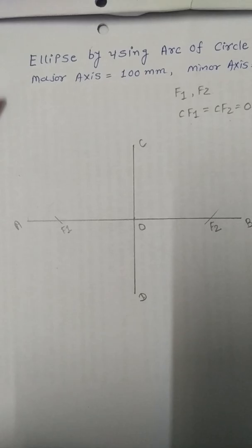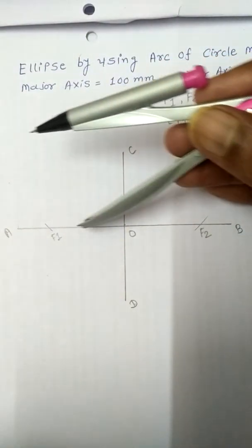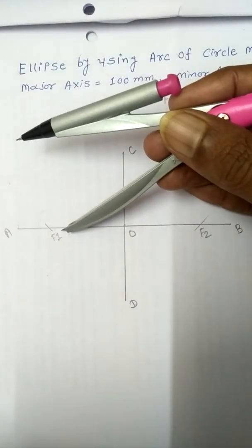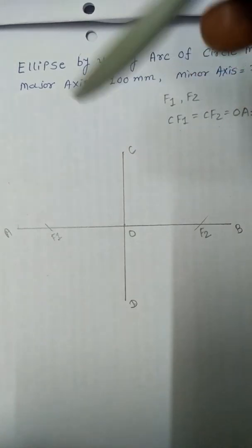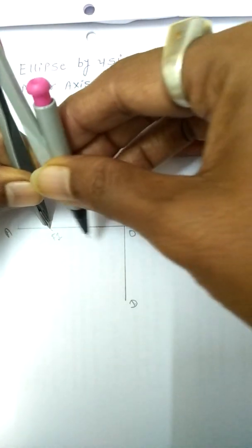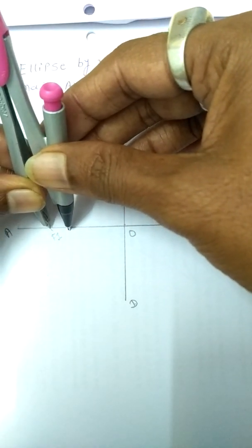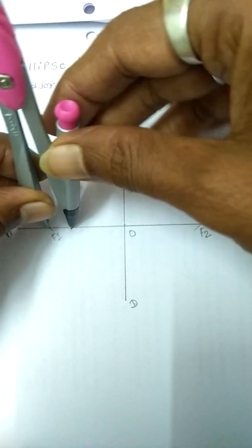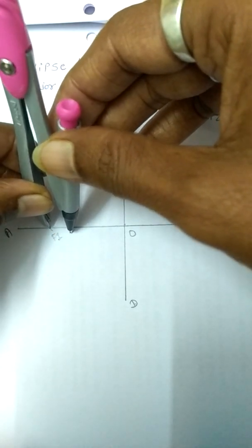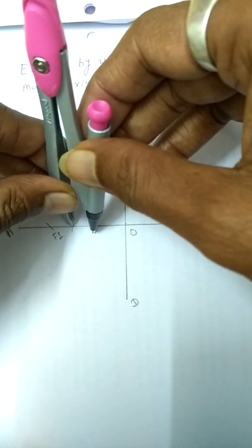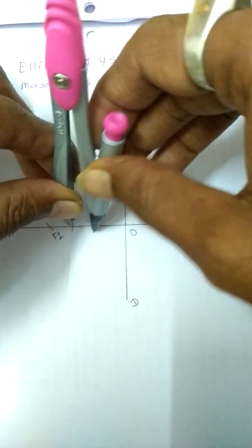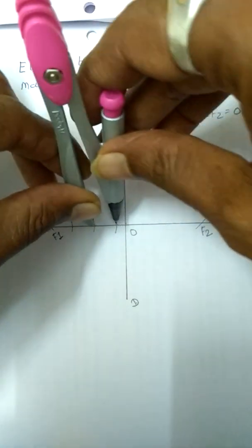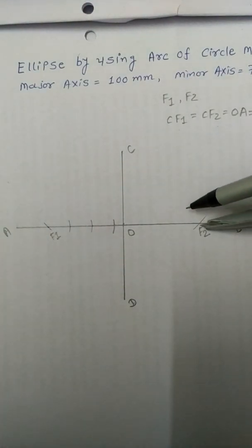Okay, now from the point F towards the right hand side, we require to divide this distance into equal segments. For that purpose, we can take each segment of 1 centimeter or each segment of 0.5 centimeter. It means you can take 10 mm or 5 mm. Let me take small arcs at equal intervals. Randomly you can provide any of the arcs. Suppose I take the first arc from over here. Without measurement of a particular dimension, directly you can plot an arc over here. So I have marked an arc. You can mark an arc also from here.